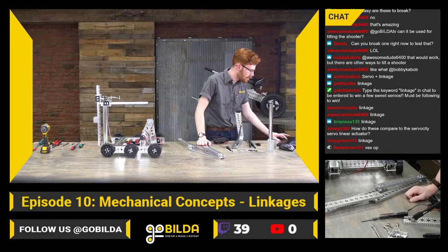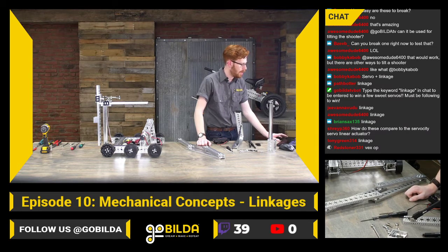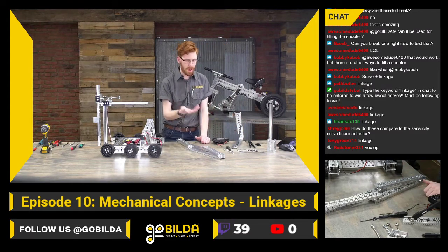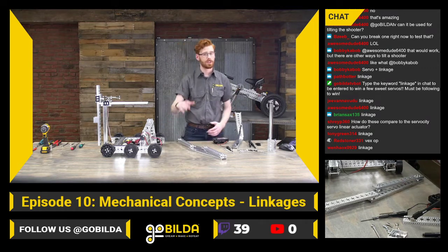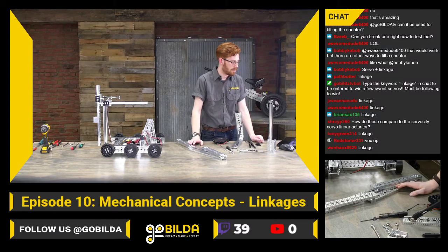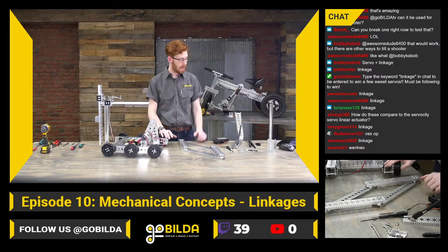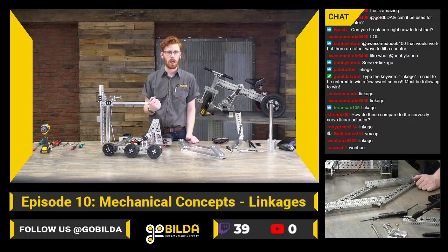How do these compare to the Servo City linear actuators? So I think it depends a lot on what linear actuator you're comparing it to on Servo City. The heavy-duty linear actuators are going to be a lot different weight class. They're going to pull about 10 amps at stall, and these are going to pull about half an amp. So you're going to pull 20 times as much power, at least, because you're also going to look at a higher voltage. But if you're comparing these to the Servo City linear servos, the Actuonics linear servos, I think these are a little bit better. They're digital, and I think they can put out a little more power for what they're rated for.